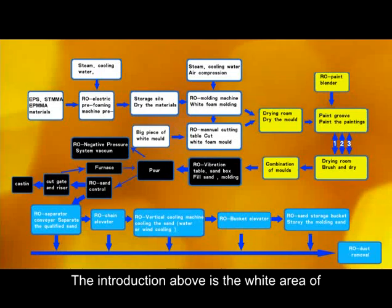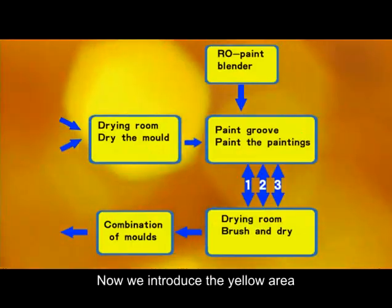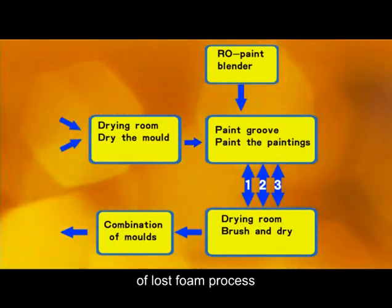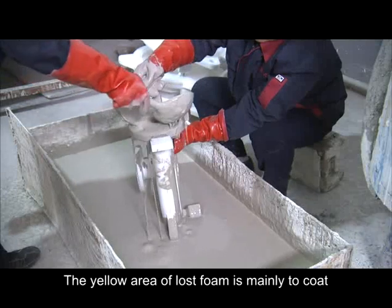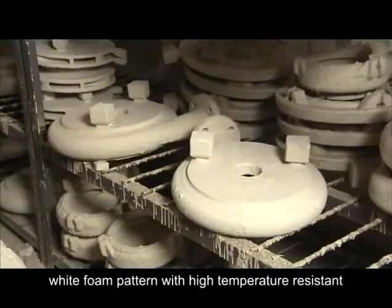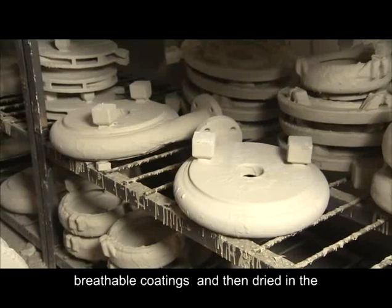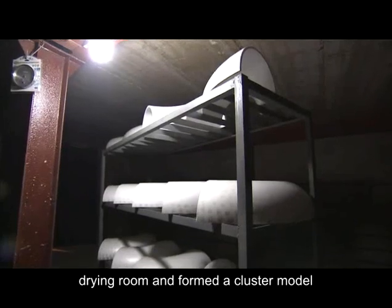The introduction above is the white area of the lost foam casting process. Now we introduce the yellow area of the lost foam process. Yellow area. The yellow area of lost foam is mainly to coat the white foam pattern with high-temperature resistant breathable coatings, and then dry it in the drying room to form a cluster model.